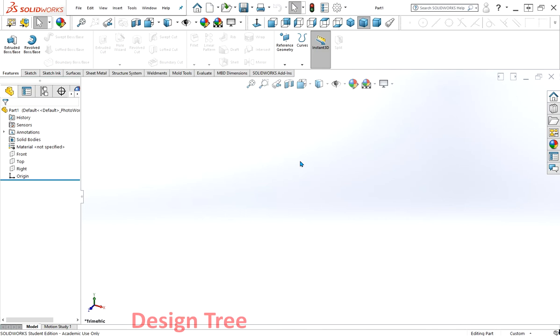SolidWorks operates in a different way to 2D CAD, like AutoCAD. You basically build up, as I say, features, design rules, relations, and that sort of thing, and I'll come on to those in a minute. SolidWorks runs through these to generate the model. So you don't really need to draw anything very accurately at all. You're actually telling SolidWorks a whole list of functions, if you like, as to what produces the model.